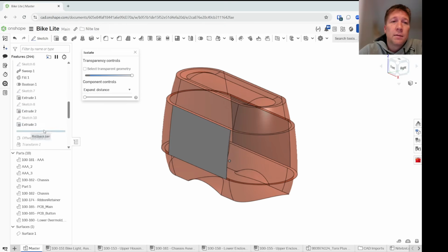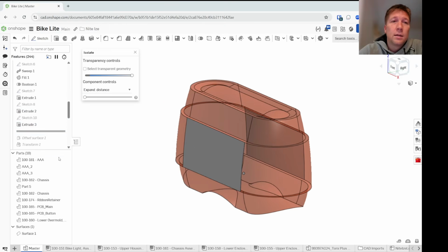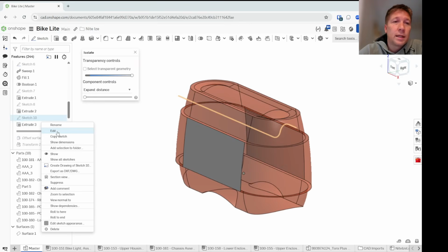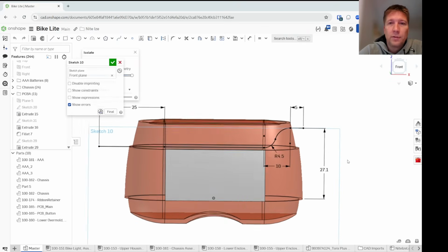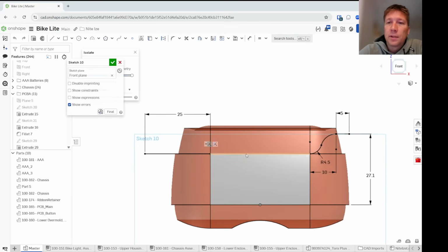All right, so the next thing that I'm going to do is take this sketch. I'm going to create a sketch right here using a couple of straight lines that are coincident with this parting line, and then estimating these dimensions to these curves. I'm saying we got about a 4.5 millimeter diameter, and then we're setting the overall height up to this point. This shape is arbitrary, but it's close to what the device looks like in hand, so that's where I get the dimensions from.